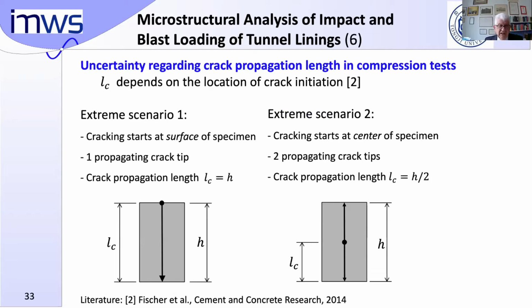Well, unfortunately, there's an uncertainty regarding the crack propagation lengths in compression tests. The quantity L sub C actually depends on the location of crack initiation. And Dr. Binder considered two extreme scenarios. Extreme scenario one is characterized by the assumption that cracking starts at the surface of the specimen.